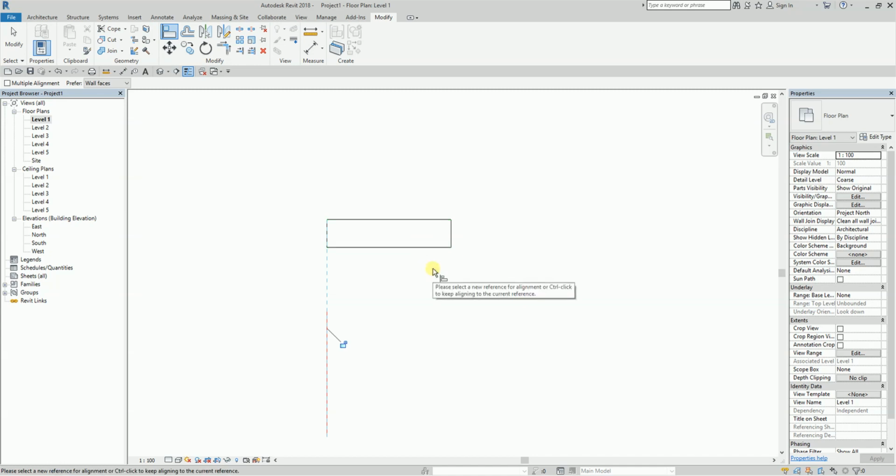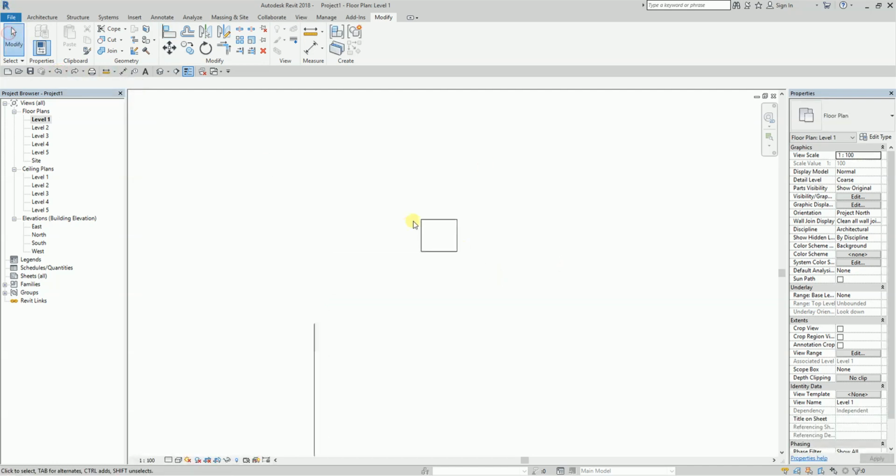If you want the square or rectangle that you have created to be fixed, you need to fix the size of that rectangle. To do that, I'll just select undo here. Then I'm going to group these lines to make them a single model. So how to group?